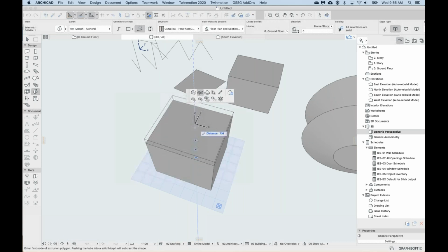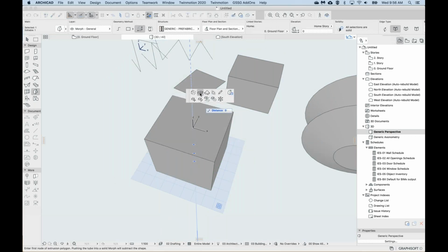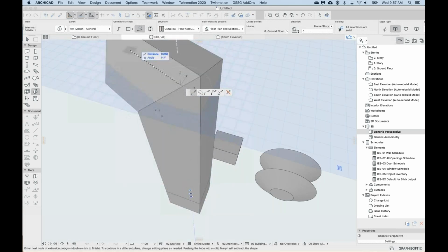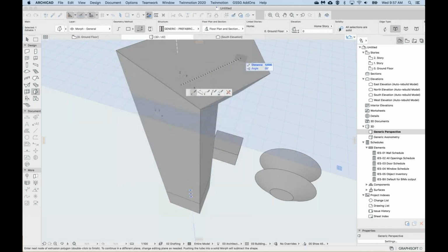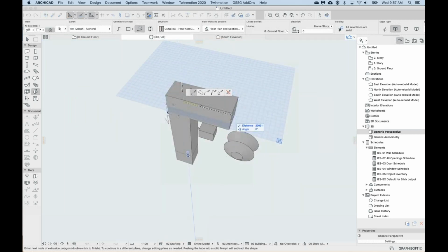So I'm using the tube on, okay, so do that again. Select the morph, click on the top surface, use the tube command. Now I will push up, and now it will want to say, where is the new direction? I'm going to move my cursor around, find one of the X or Y coordinates. As soon as it turns yellow, I'm going to hold Shift to constrain.